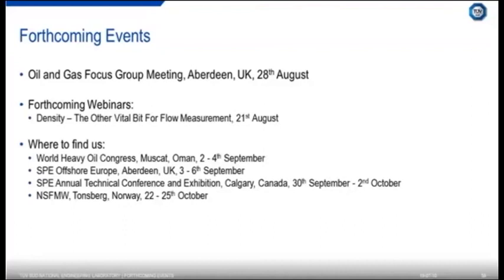We've got another question here, which is, how do you simulate field life in erosive conditions for a valve? So the way we do that at NEL in our test rig is, well, the main way we do it is increase the sand concentration. So in the field you might have a valve and the sand concentration is a fraction of a percent. It's obviously not practical to test that in the lab because you're probably going to get little to no erosion over many hours of actual test work. So the way we accelerate basically the damage in the valve is to increase the sand concentration.